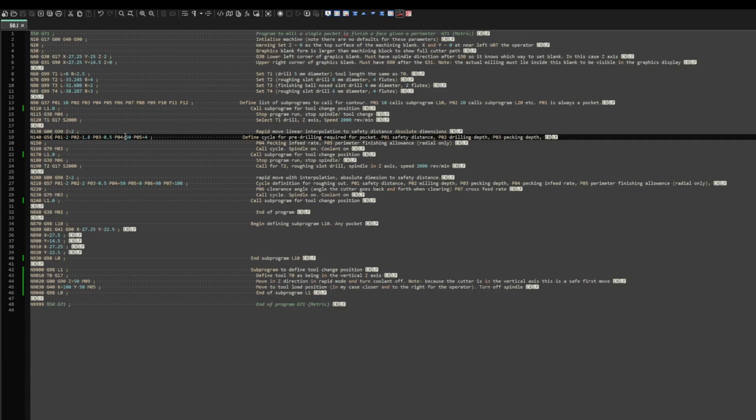In fact, you can use the suggested drill up here, but if you do, you might risk clipping down the side of the part you've squared up. So you can either make sure the drill is small enough not to do that, but only big enough to do the centre part of the slot drill, where it might have trouble. But you don't know where the machine is actually going to create this pre-drill hole.